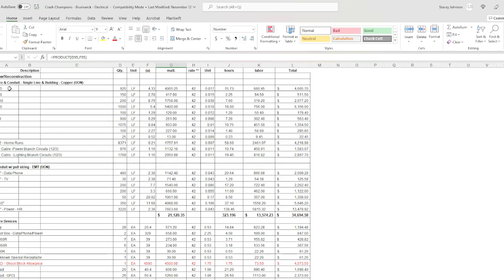The way we break it down, we have a section for our wire and our conduit, including the wire for the single line, and then MC cable. Most of the branch circuitry can be run with MC cable, where all of the home runs, of course, have to be number 12. Or if it's a particular type of mechanical equipment, it's going to tell you that you need 3 number 10s and a number 6, or vice versa, and you'll know from that.